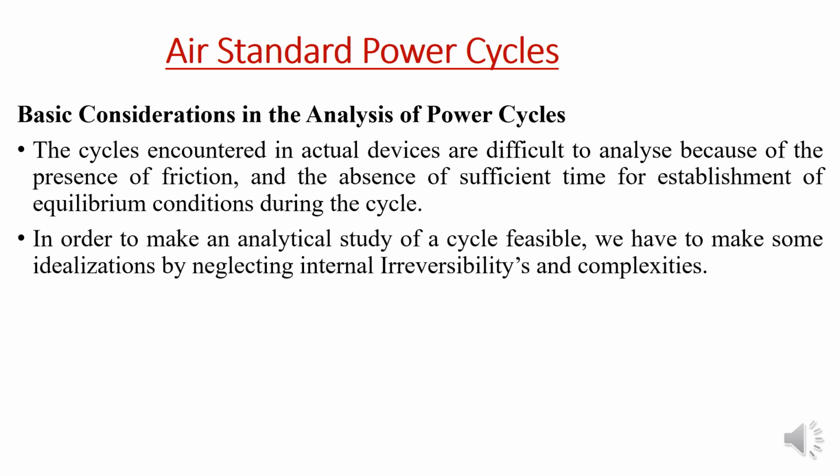So we are going to make some assumptions, because in the pipes connecting different parts of the cycle there will be bending losses or frictional losses. These are the losses we are not going to consider while deriving any equation or analyzing any power cycle. That is the basic consideration we are going to take.